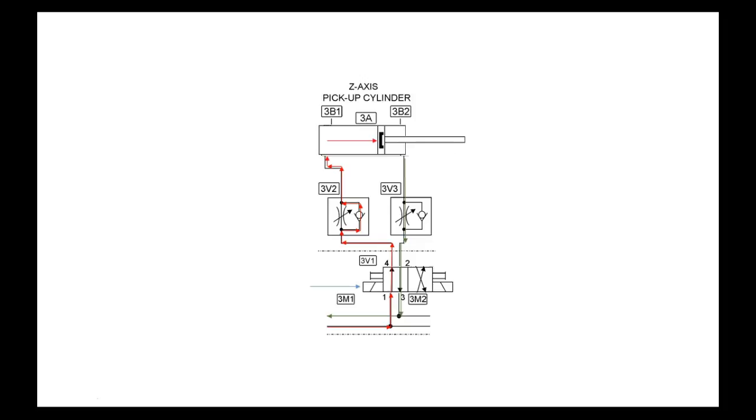So this is electrically pushed, right, with a solenoid. What's this? That's manual override. And they're not easy to get to. On a lot of relays, they're real easy to manual override. These you usually have to have an Allen wrench or something very small to get in there and push on.